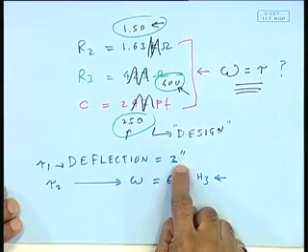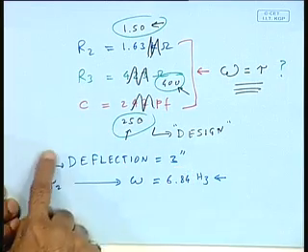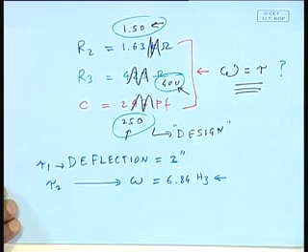You can find out by putting certain values for R2, R3 and RC what value of performance you're going to get. You can derive that using SPICE. You can do the same thing for this one also. It's not very difficult to do that. So I'm able to simulate that. I'm also going to be able to simulate noise by using a little Monte Carlo. I can simulate that noise.